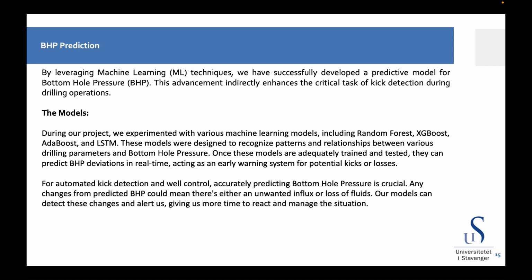For automatic kick detection and well control, accurately predicting bottom pressure is crucial. Any changes from predicted bottom pressure could mean there's either an unwanted influx or loss of fluids. Our models can detect these changes and alert us, giving us more time to react and manage the situation.